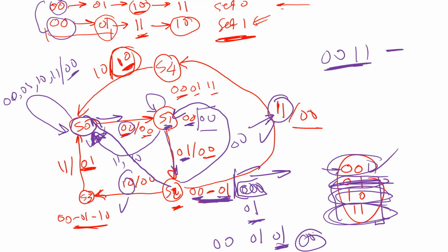So what you have to do here, number one, you have to finish this state diagram. After you finish this state diagram, I want you to make the state table, and once you have the state table, you need to find the input equations of the flip-flops. We're going to use D flip-flops. Also, you need to find the equation for the output. Remember, we have two outputs. Okay, so let's start with the first one.